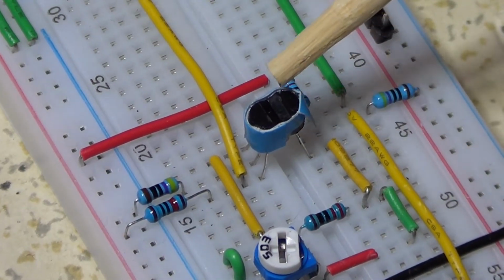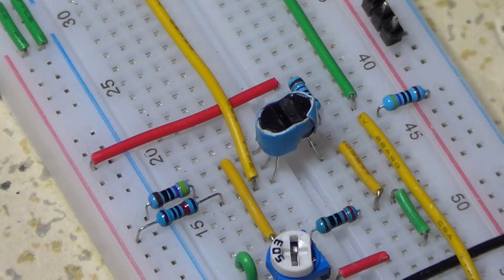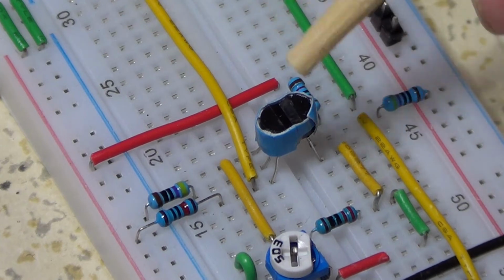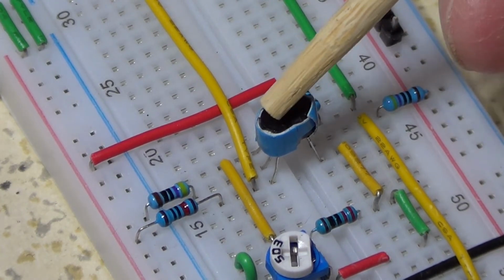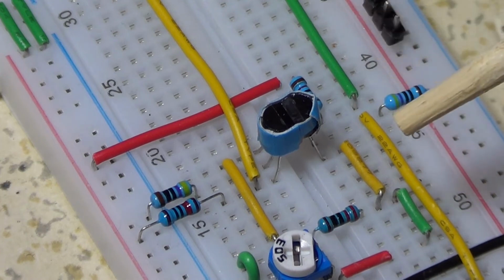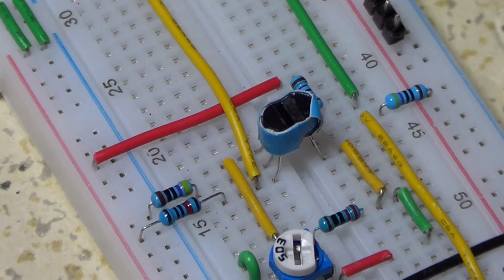These two transistors are connected back to back, and they are taped to each other so they cannot move. And this is thermal tape, so it will help distribute the heat generated from one transistor to the other, so that they basically have about the same temperature. And this is very important, as we explained already when describing the schematic, to make sure that the sine wave has a symmetrical shape. These are the two controls for the system, and the output is right over here, as a sine wave. So let's check it out.